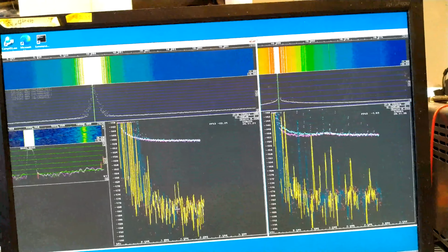The SDR-IP gives a flat curve here at minus 182 or minus 181.1. And the imaginary part is well below, around minus 192. It seems that with this long measurement time I could make reasonably reliable measurements down to maybe minus 188 or so.